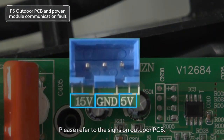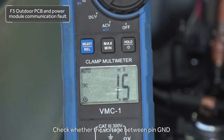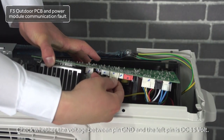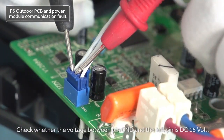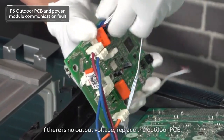Please refer to the signs on the outdoor PCB. Check whether the voltage between pin GND and the right pin on the blue terminal is DC 5 volts. Check whether the voltage between pin GND and the left pin is DC 15 volts. If there is no output voltage, replace the outdoor PCB.